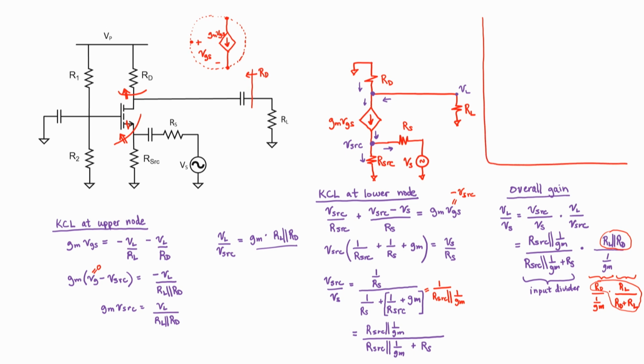By inspection from the original circuit and going left to right, we have a signal voltage V sub S. We then have a signal resistance R sub S. We then have a source resistance R sub source. We now have a little resistance 1 over Gm, and that's it for the source side. You'll see that our input voltage divider matches our little diagram right here just nicely.